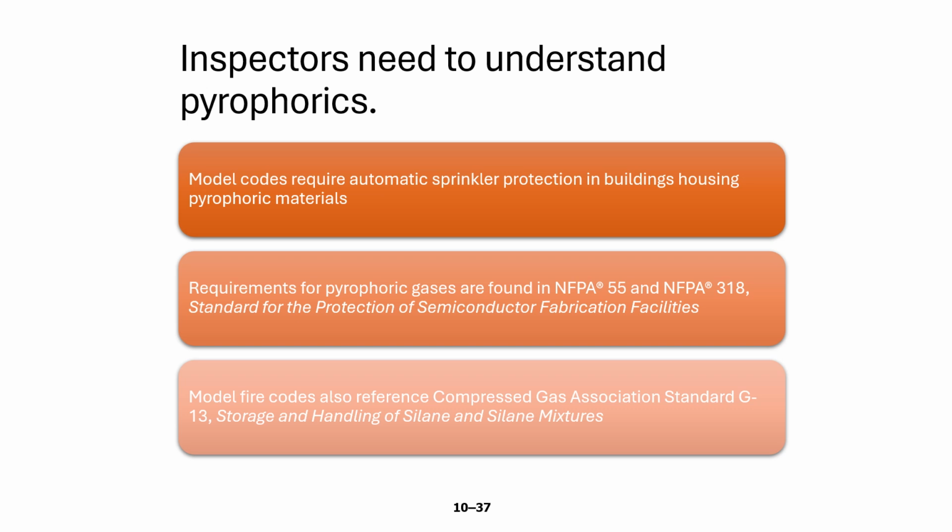So requirements of pyrophoric gases are found in NFPA 55 and NFPA 318, which is the standard for protection of semiconductor fabrication facilities. Model codes also reference the Compressed Gas Association standard G13, which is the storage and handling of silane and silane mixtures.